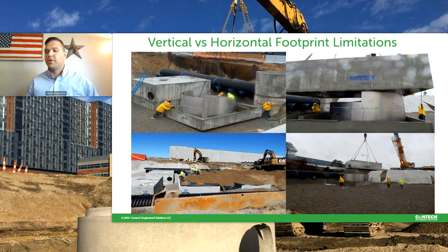Well, as I've said probably 3 or 4 times now, the depth associated with the sump on a manhole for this application was deep. It was 25, 30 feet deep almost. When you have groundwater table like that, that's just not feasible. So we elected to go with a vault style. This shallower vault was huge for us because it allowed the treatment and the bypass to still effectively happen within a singular structure, and it still was feasible for the contractor to put in the ground.